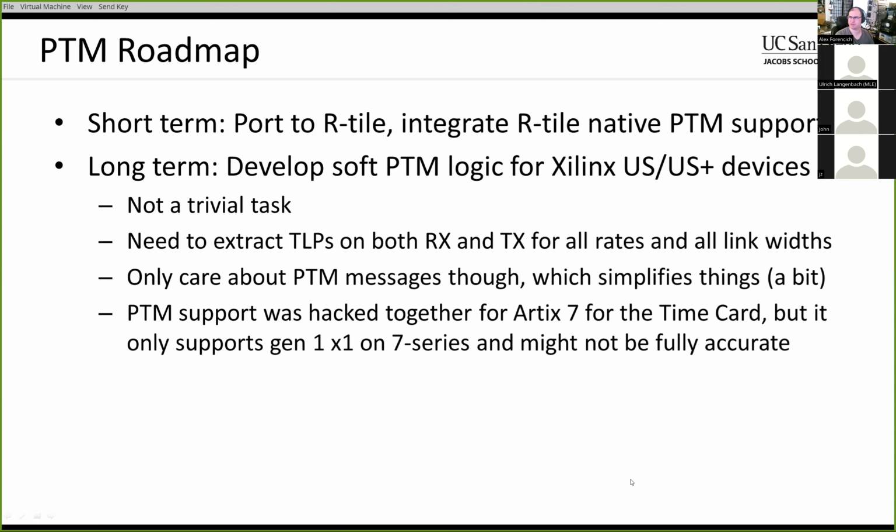What are the capabilities of those dev kits? Is that like a nice PCIe form factor thing? Nope. It's more like the ZCU106 kind of form factor. Okay, so it does have some PCIe, but it's not a small one. Yes, it's a big one. It's a PCI Express card, but it's not compliant and it's too large in the direction where you can't fit the lid on. Okay, but at least it's a decent thing for developing Corundum.